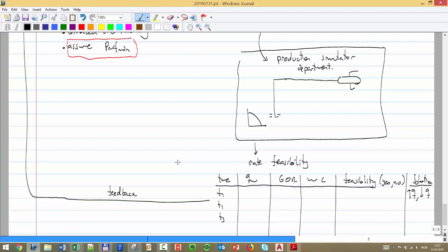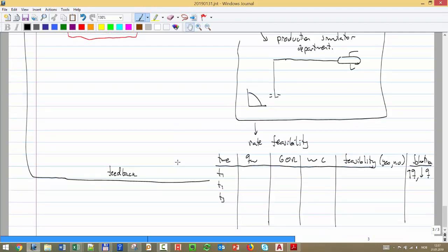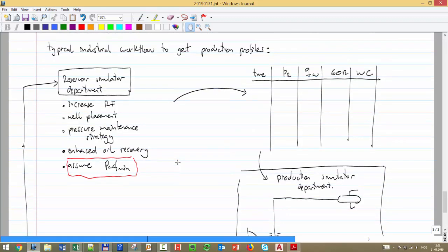So why do we have to take many loops? Why cannot it be just one loop? The thing is that when you do a change in a rate in a given time, okay, it's going to affect all subsequent rates. So you might say it doesn't work in time 3, but it's going to affect, because you're draining less from the reservoir, so it's going to affect all other times. So if they adjust, they come back here and they run, now they have to check once more. And again the cycle is repeated.